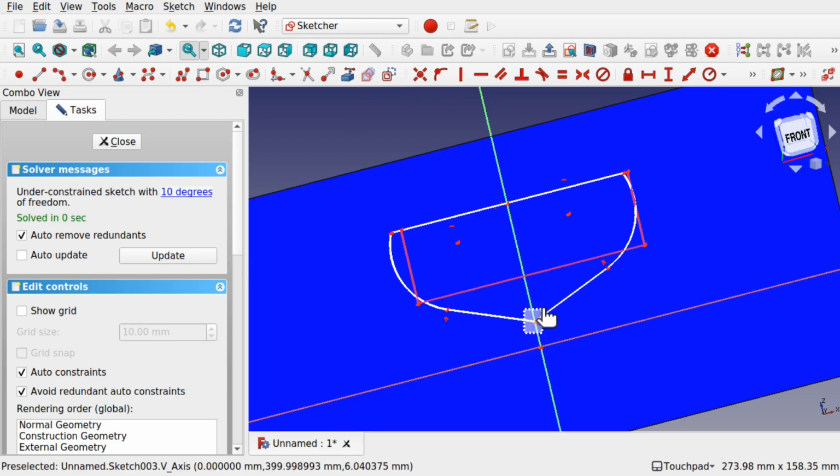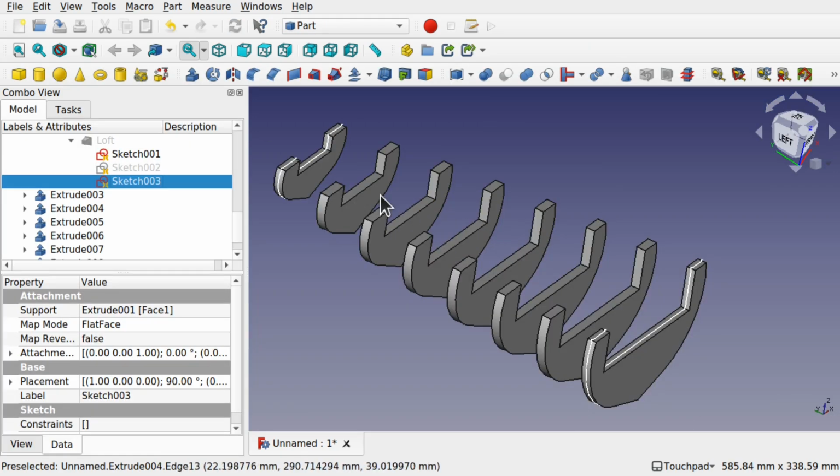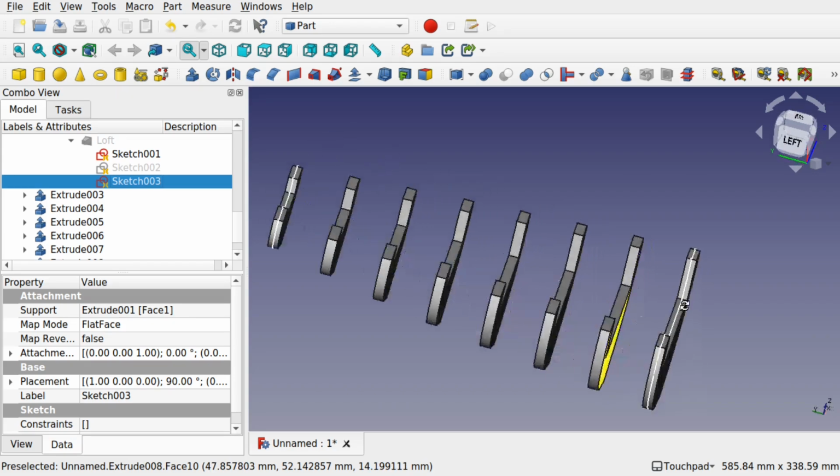Constraint and coincident constraint along there, and use a box in here. Hit escape to delete the top. Trimming. And hit close, and you can see how that's taken across there.